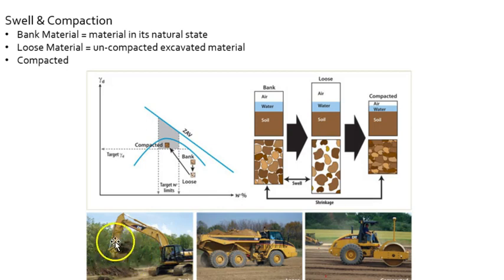Once material is excavated and taken out of the earth and placed in trucks, then it is loose material. And once that happens, just kind of intuitively, if you dig a hole in the earth, the size of the pile of material is going to be larger than the hole, because now a lot more air has entered into the composition.